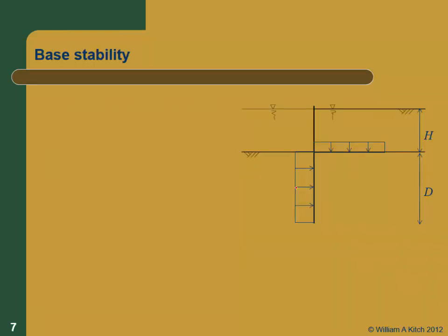All right, so let's talk about basal stability first. Basal stability is generally a problem when we have clays. When we have sands, that's generally not a problem. Again, we're doing this in the most typical application for sheet pile walls, where you're in a marine environment. You've got water on both sides of the wall. So again, in the upper part of the wall, we just have gamma prime times H, the vertical stress that's applied here.